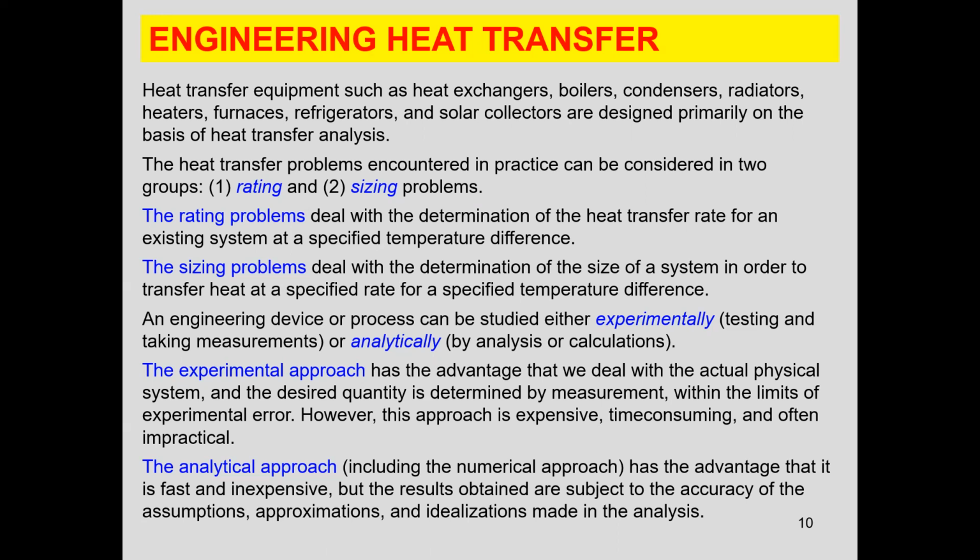When we're dealing with heat exchangers, boilers, condensers, radiators, heaters, furnaces, refrigerators, and solar collectors, the rating problem deals with the determination of the heat transfer rate for an existing system at a specific temperature difference. Whereas the sizing problem deals with the determination of the size of the system in order to transfer heat at a specific rate for a specific temperature difference.